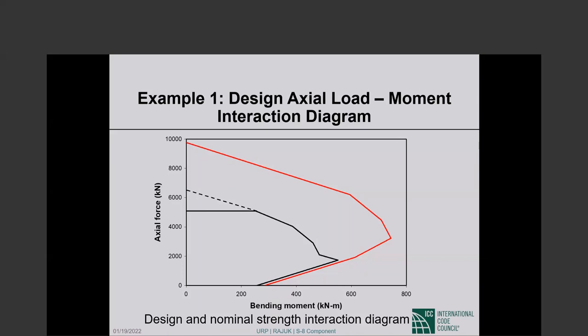So there is nothing that tells you that reinforcement cannot be lower as you go down the building. It typically isn't, but for instance, if you increase the column section, then the reinforcement can decrease, and there is nothing against that. Maybe you have a slightly larger section at the lowest level. But yeah, there is nothing against it.